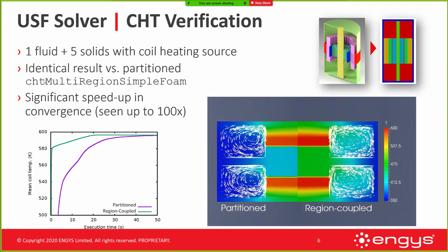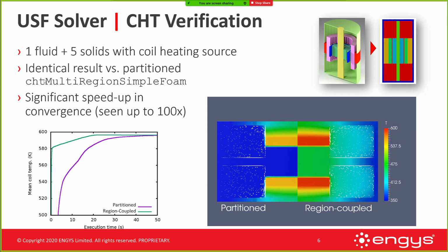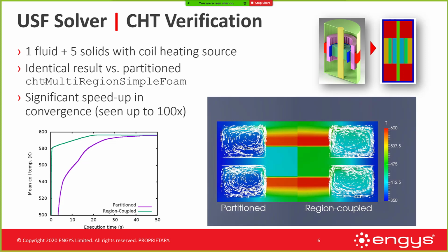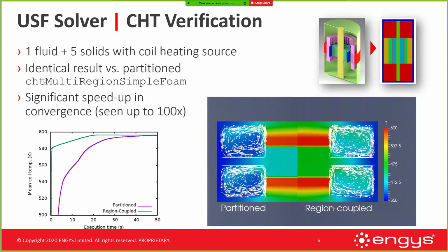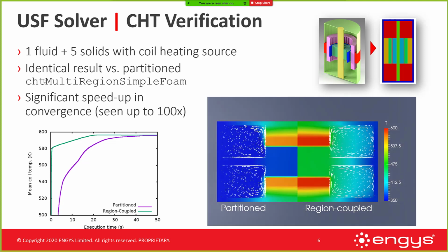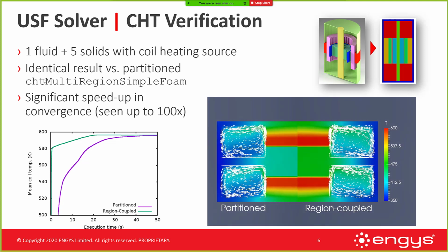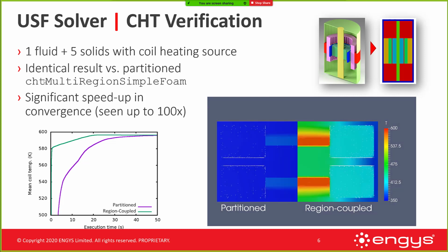There's significant speed up in convergence. In this case, we see speed up, and in other cases, we've seen up to 100 times speed up. So this is very problem dependent. If we did all solids instead of a fluid and several solids, we'd see the USF Solver converge in one iteration.